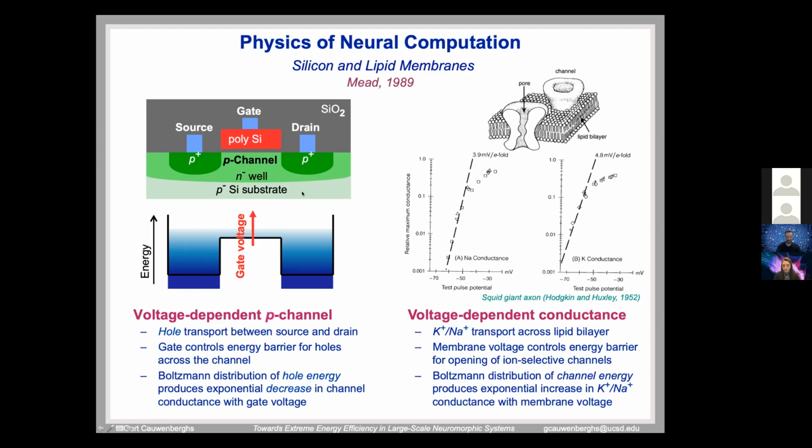So what Carver realized is, let's make circuits that can take advantage of the same mechanisms, and directly, innately implement what is done in biology, with subthreshold transistors and this orders-of-magnitude dynamic range with currents, from femtoamps, or maybe picoamps, up to hundreds of nanoamps. That gives you several orders of magnitude of range. And there are also small currents, which means low power consumption, which can be harnessed if you do it right to get low energy per computation. That's the beauty in a way.